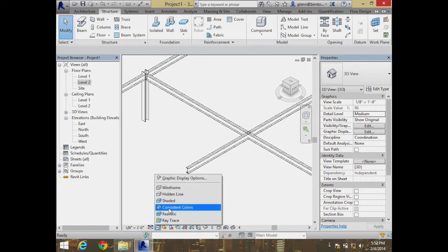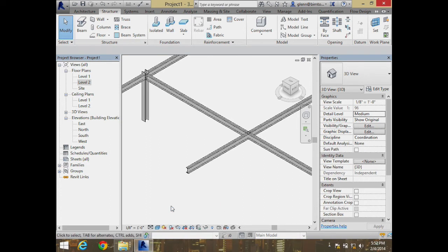My problem is right there at that corner. Back over here, we're going to be okay. I can lower that down and have it on the bottom of the connection. Over here, this one I'm in trouble with because I can't really have two things passing through each other. So what am I going to have to do? I'm going to have to lower this beam and have this one coming across it. Okay, and that'll actually work out for us.